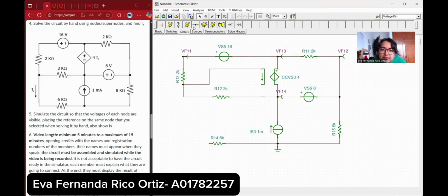And for measuring current, we can select this icon, that's current arrow, and we select it facing the direction we need the current to be going. So this one's going to be down. Now, why did I delete this one and why did I delete the cable? Because again, this is a current that should be connected in series. So we need to be really careful with making this connection because again, this is a very sensitive software. Yeah, it's correct. This is correct.